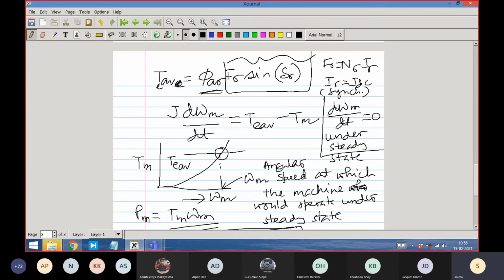So is that clear, that a synchronous machine, when it is loaded more or less, is actually adjusting the delta to more or less? Because the synchronous machine has a constraint. Synchronous rotor current has been frozen. It is a DC current and I am just controlling it. I am passing 40 ampere DC current. Done. But the machine has to produce torque. How will it do it? Why does the machine have to produce torque? Because unless that torque is produced, it cannot balance the mechanical load torque.